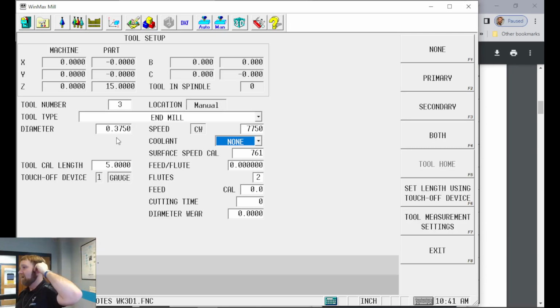I wish I could go pull out the calculations. 15 years ago when I went through this program, okay, 15 years ago, our cut speeds for the tooling we had then was 600. Okay, the equivalent of today's tooling. Tooling has come along to where they're basically still carbide end mills, but they've changed some geometry, they've changed some coatings to where now you can run them at 1,000 and some much higher. There's some really high performance stuff that has cut speeds up in the 2,000 and 3,000s that you can use.